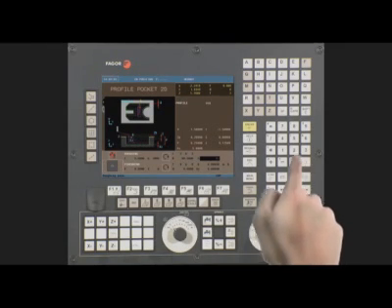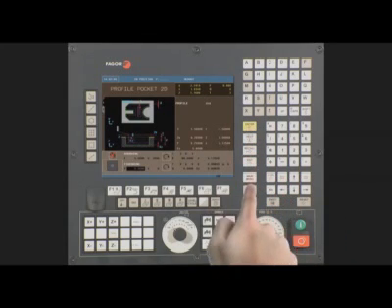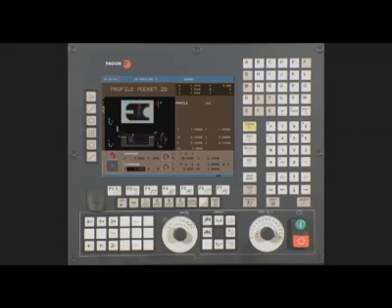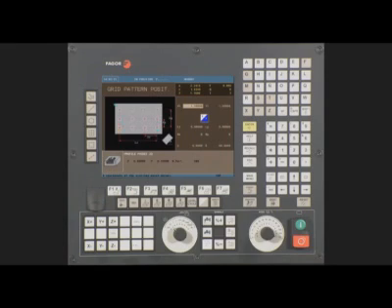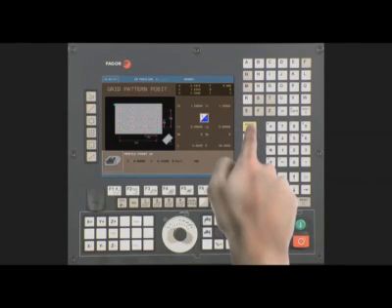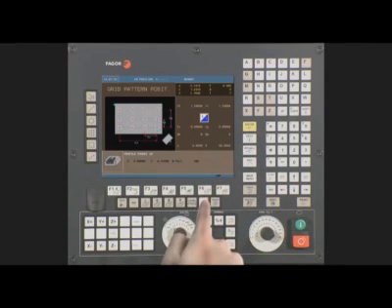Press Enter to continue. We will not be doing a finish pass, so please confirm that our finish tool is set to 0 under the finish section. Now combine the operation with grid pattern position. Press the grid pattern key. The cycle takes our X1 and Y1 from our previous cycle. Use the half key, select operation 1 of 3.